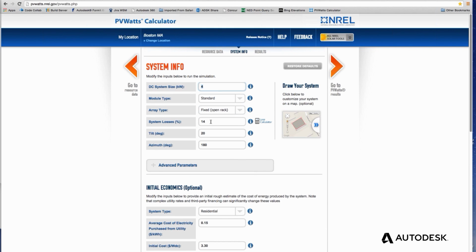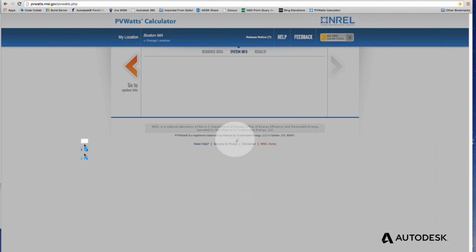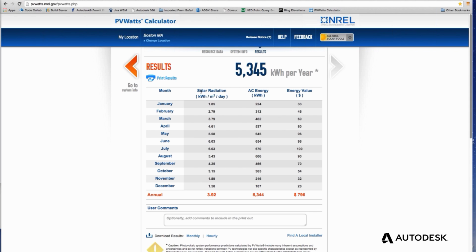Yes. So then I can just put in some values for a fictitious solar panel and its orientation. So I'm just going to design a flat panel, input the angles, how it would be rotated in 3D space, and then let it analyze that panel. And it will give me back the solar radiation for that location and that panel orientation. So this comes out to be 3.92 kilowatt hours per square meter per day average. If I multiply that number, it comes out to be 1,430 kilowatt hours per square foot.